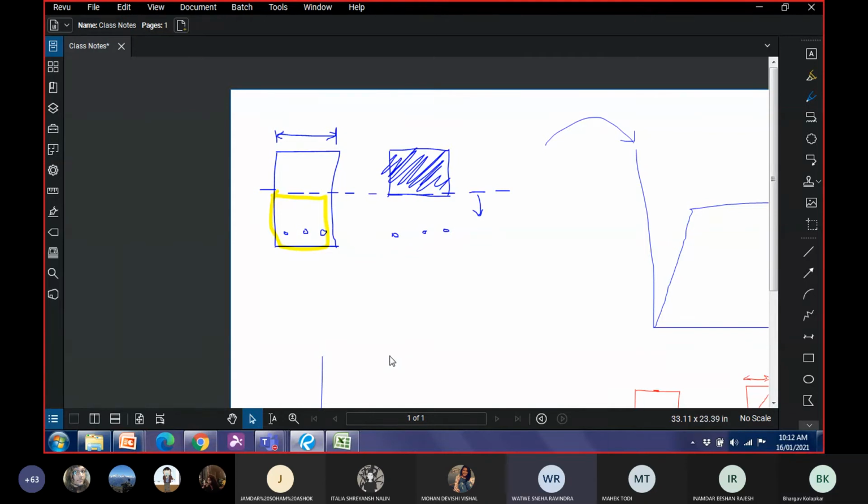The steel bars are taking up the tensile component completely, and the concrete above the neutral axis takes the compressive stresses completely. That's fine. But why do we make this assumption that concrete does not take any tension? Neha, you've already answered this question at the start of the lecture. So I'm just asking you to repeat your answer.